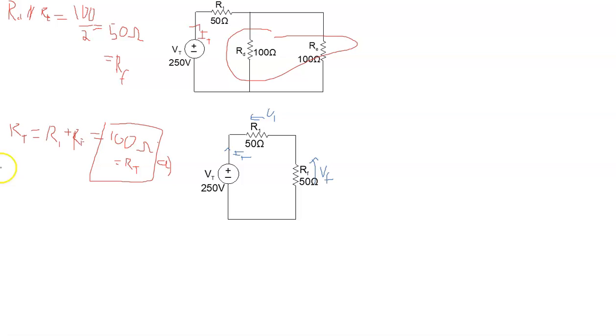Okay, so part B will ask us now to calculate IT, and I'll usually start off all my examples that way. It's not necessary, I suppose, but Ohm's law says that IT is equal to VT divided by RT. And again, I'll note that VT is not the voltage drop across any one resistor. If there was a resistor directly in parallel with the source, then we would be able to find one of the currents before we started. And you will see that now and then. Not in any of these examples that I've presented, but it does show up.